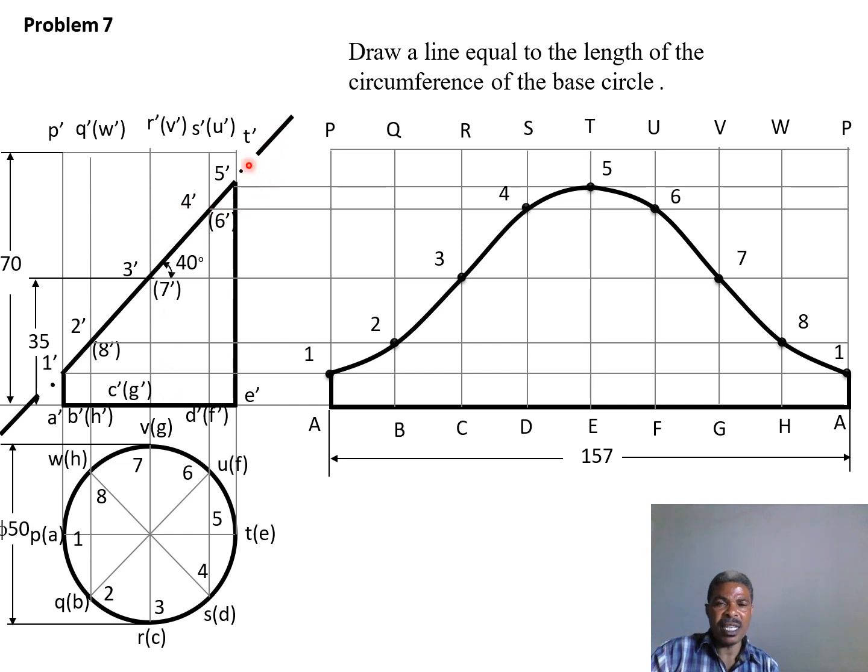And it's being inclined at 40 degrees from horizontal. If it's measured from the horizontal plane, it's 40 degrees. So these points, as we have said for the previous cases, we have to project them upwards until they intersect with the truncation line, the cutting plane here. So we will have to extend or project them in this direction to the end view.